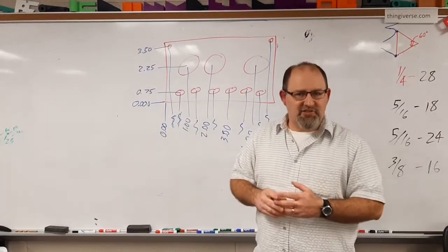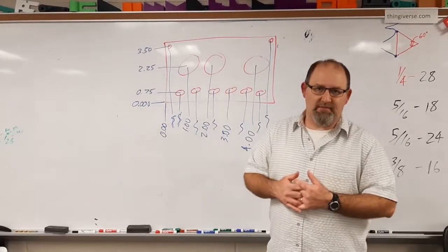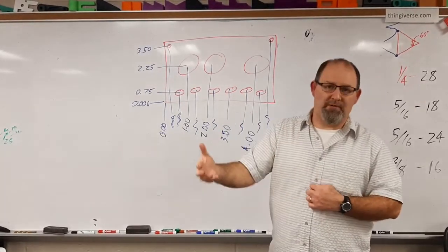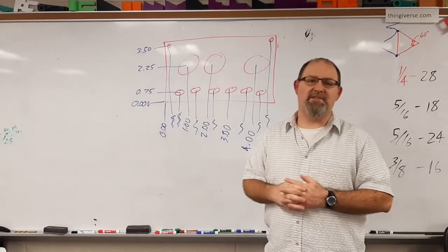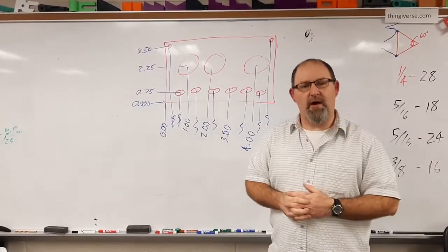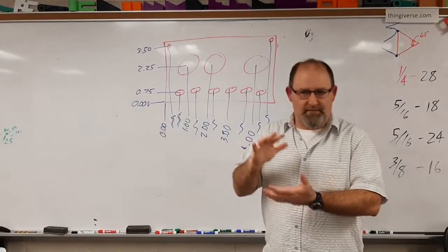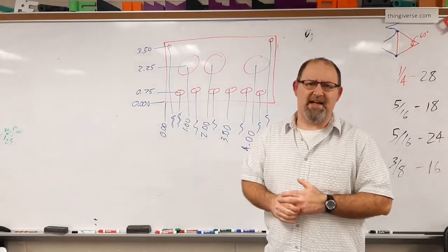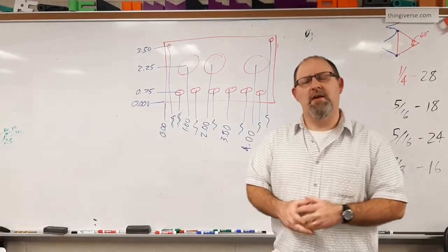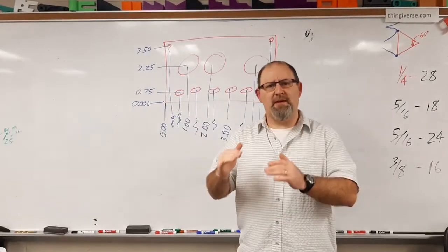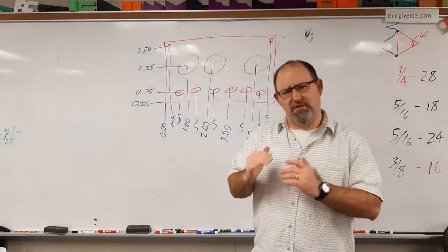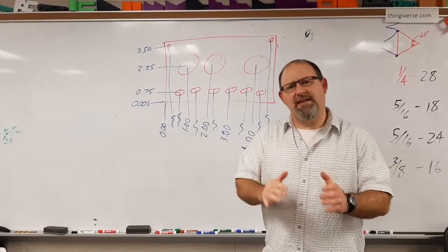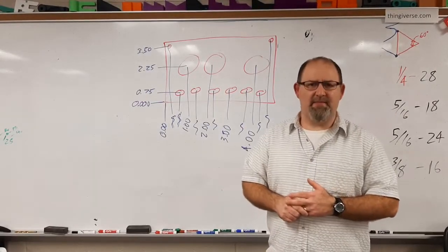Datum dimensioning is generally a more precise way of dimensioning. Once again, the more precise, the tighter the tolerance on the part, the more your costs go up. If you're dealing with, let's say, tool and die punching, automotive design, or aerospace design, areas that need extremely precise dimensioning, then you need to use extremely precise dimensioning.